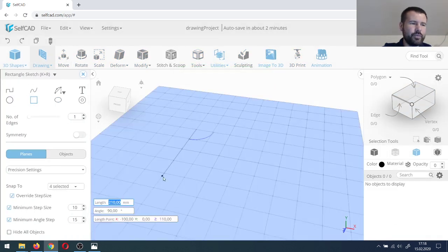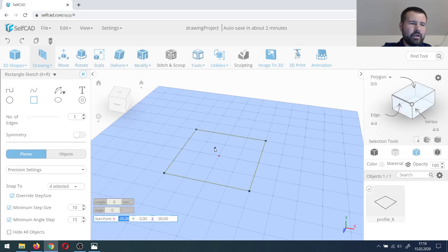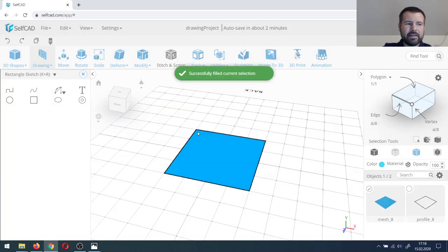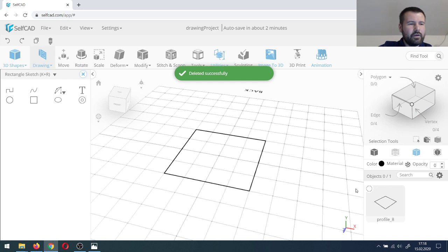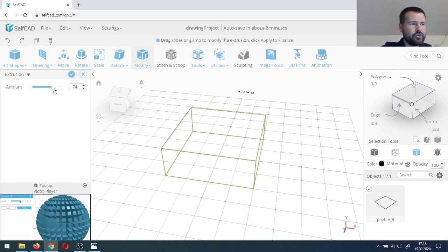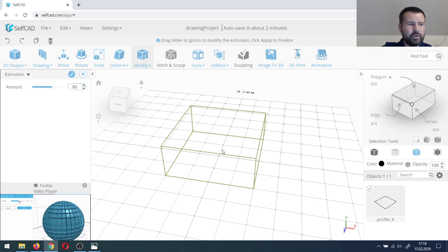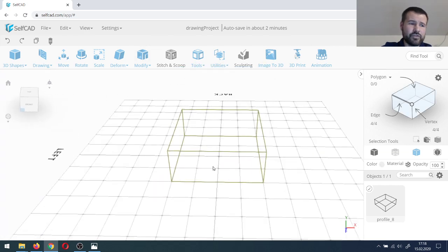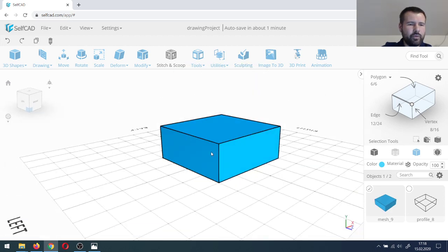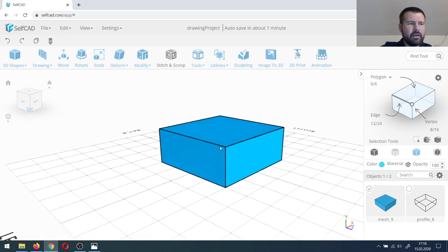I'm not sure if this won't sound confusing, but fill polygon basically is filling with triangles the currently selected profile. So if you have, for example, a cube or even some less complicated shapes like a wedge or something, you can actually just press fill polygon to generate the triangles between the edges. Triangles or quads, it depends on what we can do with the triangulation itself.